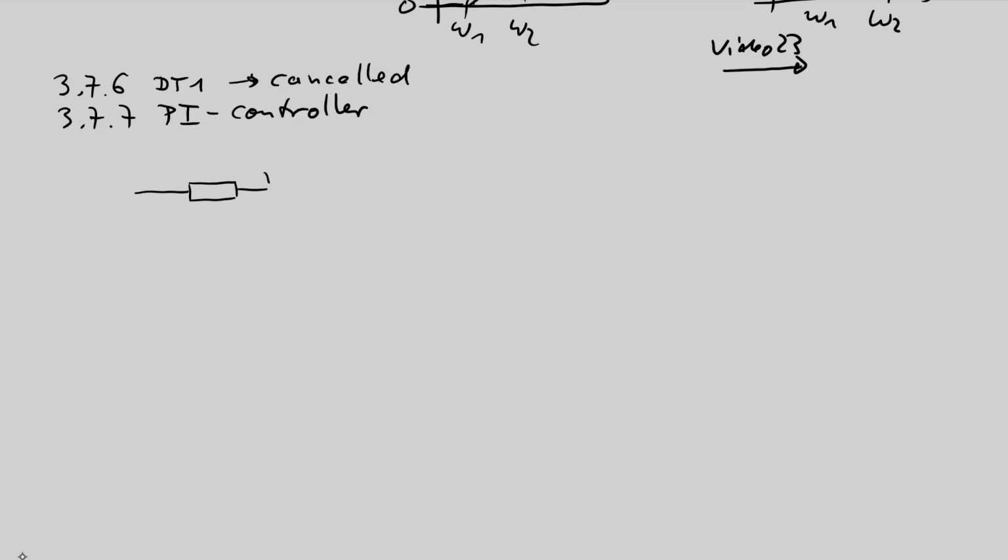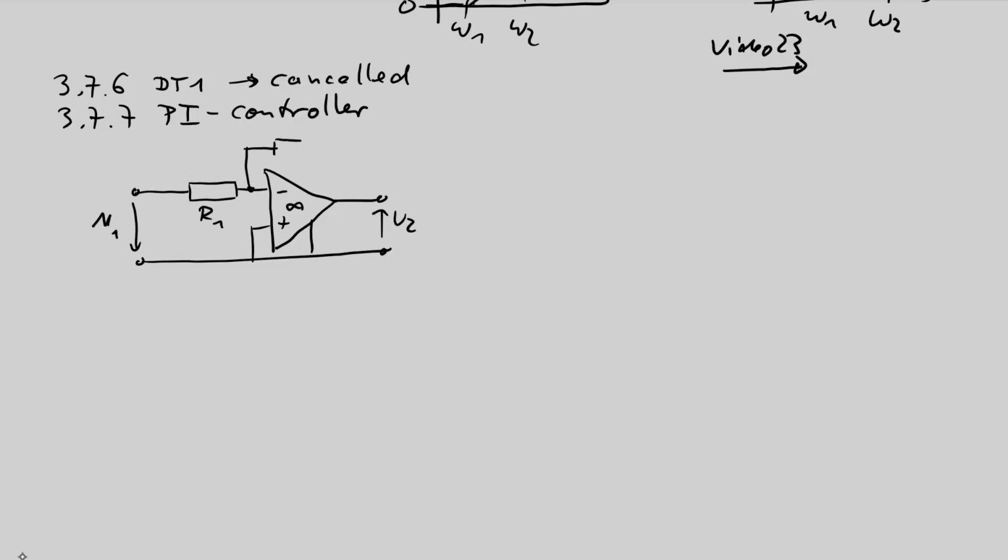There is again an inverting amplifier, three components plus operational amplifier. We assume again an ideal amplifier with hidden minus sign, with R1 as the input resistance, and now in the feedback we add two components in series connection, a resistance and a capacitance, R2 and C.